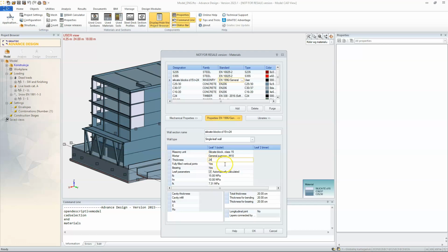I can also specify a thickness. It's a new approach in comparison to other materials because usually we had a material and the thickness was related to a certain element. If it comes to masonry material, it's done differently, because it's related to a specific block. And also, as you can see, you can use many different wall types. So it can be single leaf, it can be double leaf, it can be cavity, and so on. And the mechanical properties are steered with the thickness.